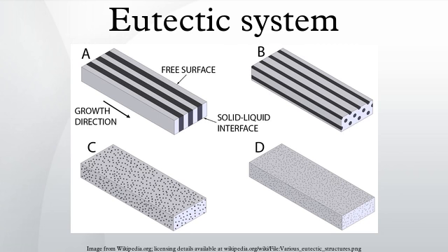Peritectoid. A peritectoid transformation is a type of isothermal reversible reaction that has two solid phases reacting with each other upon cooling of a binary or ternary alloy to create a completely different and single solid phase. The reaction plays a key role in the order and decomposition of quasicrystalline phases in several alloy types. Peritectic transformations are also similar to eutectic reactions.